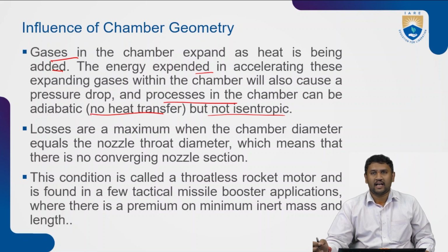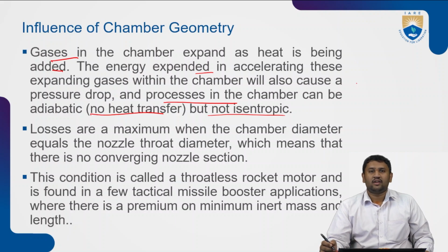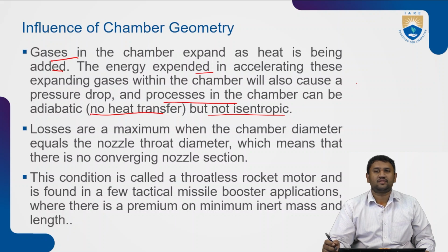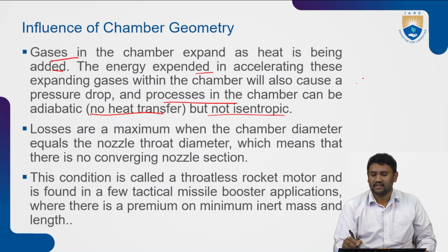The losses are a maximum when the chamber diameter, that is the diameter of the combustion chamber, equals the throat diameter, which means there is no converging nozzle section.